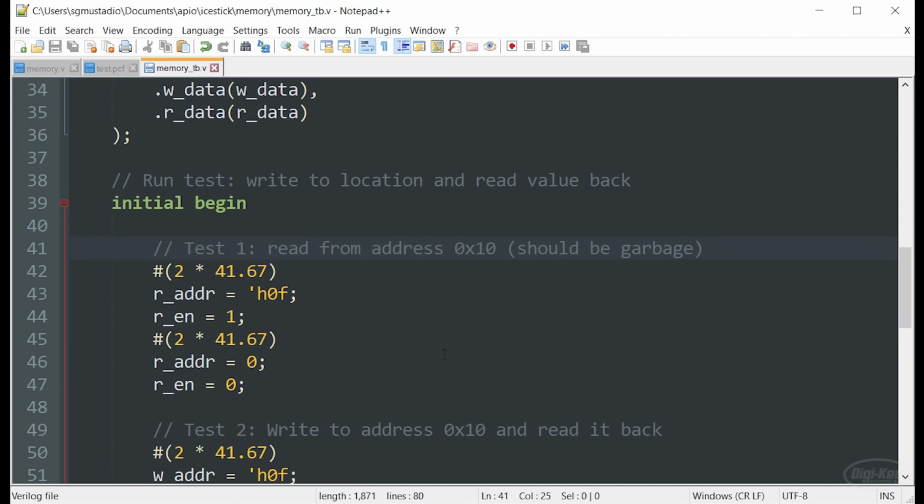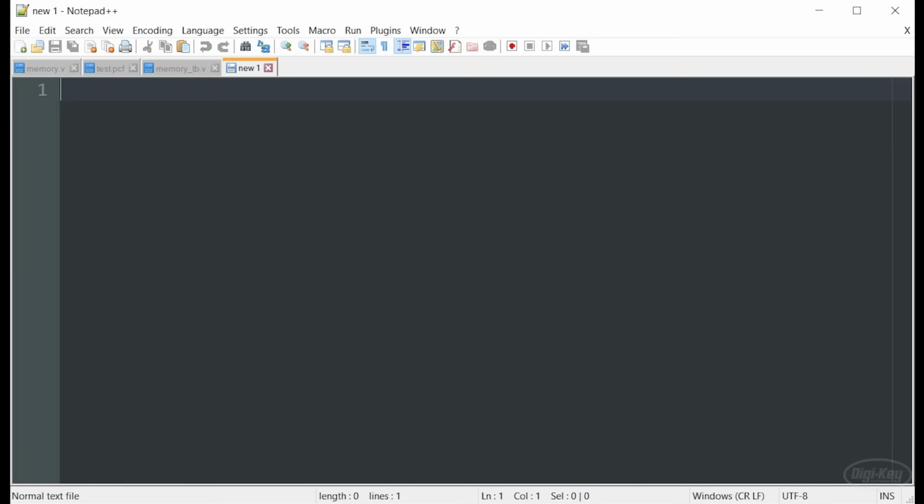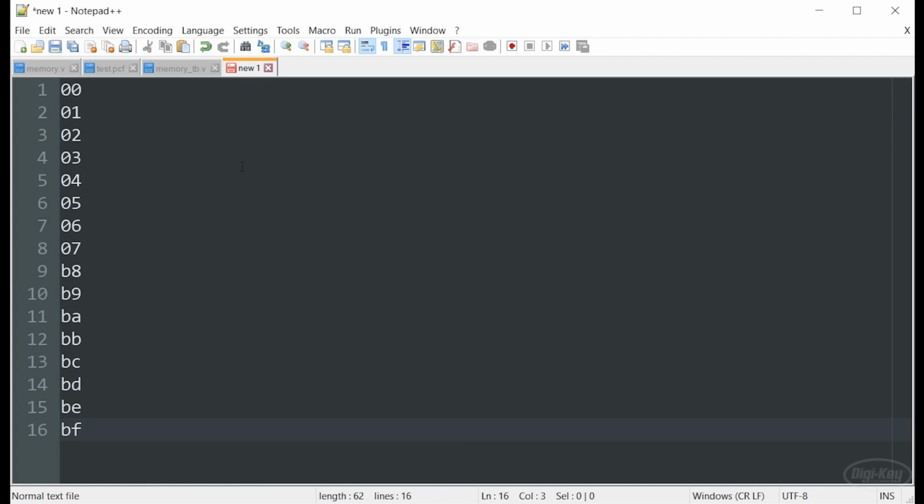One possibility is you might find a way to create something like a for loop and you walk through every element setting it to 0, but I've got a better way. Let's read from a file during synthesis and set those initial values so that they're ready to go as soon as we configure the FPGA on boot. To read from a file, we first need to create that file. In most cases, you can just do a comma separated, a space separated, or in this case, I'll do a new line separated set of values.